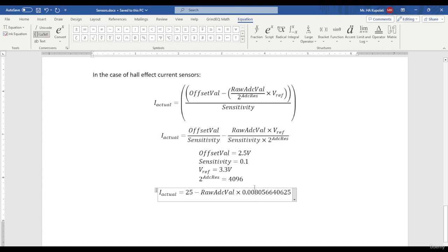Of course, you might want to play around with it, because Hall effect current sensors have certain tendencies and certain issues, and they don't always match. They're very prone to being affected by magnetic fields. So if you put them next to an inductor, well, you get what you pay for in that case. It's something to take into account when using Hall effect current sensors. But for high current situations, they're an absolute necessity. So that's about it.